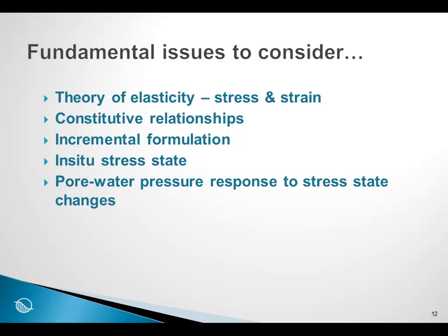In many cases, we need to say something about the state of stress in the ground before we come along as civil engineers and build structures or do something on the ground. As a result, we need to establish the in situ stress state. Sigma W has a special analysis type to establish the stress state in the ground, and then the pore pressure response due to stress state changes, which is fundamentally all about a coupled consolidation analysis.